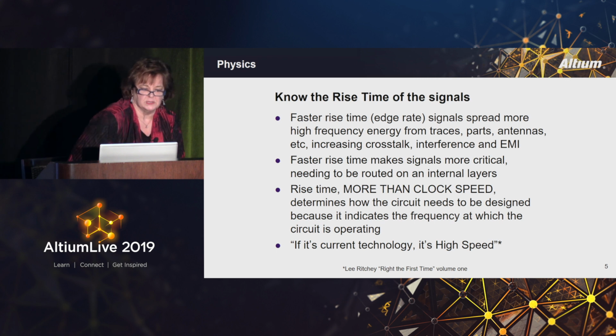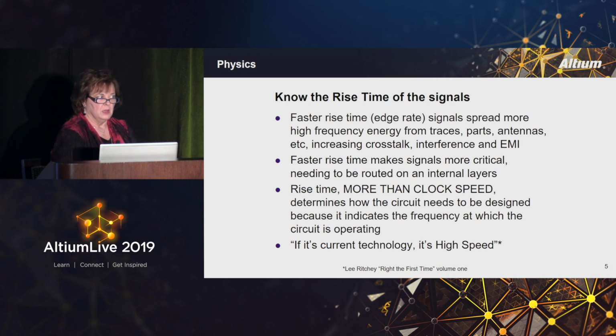So for that reason, because it is more of an issue as rise time gets faster, you need to understand what the rise times of your buses and signals are. It's because that spreads more energy, can more easily create antennas and crosstalk and all the other interferences that we don't like to have on our boards.